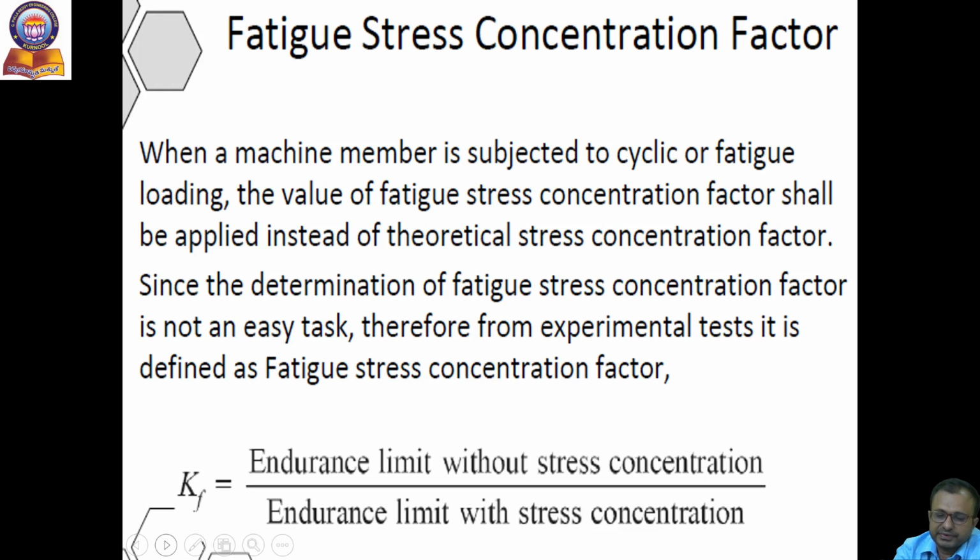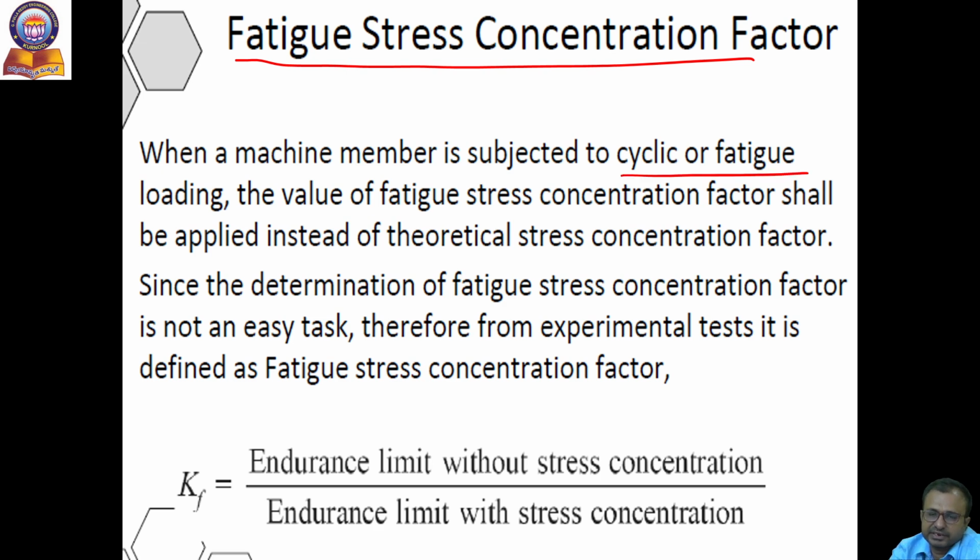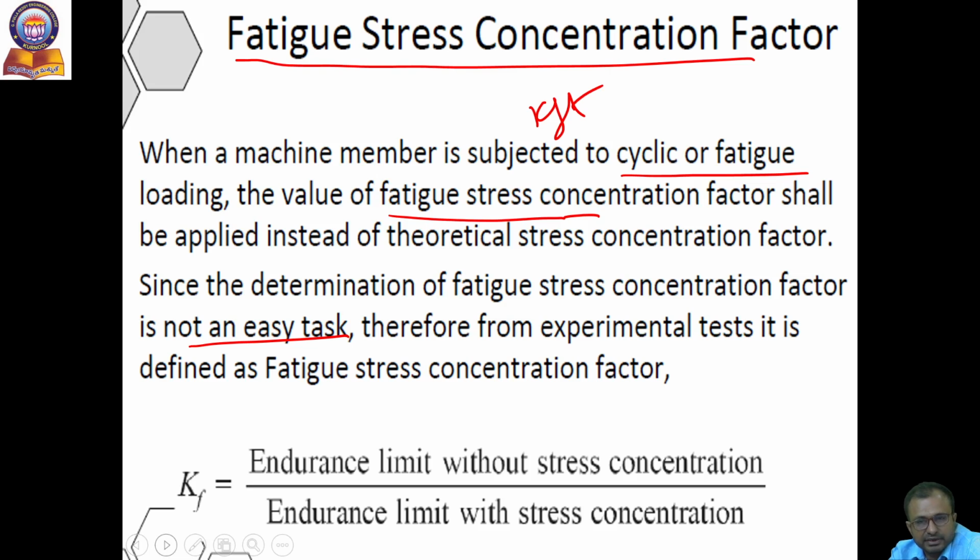Next one is fatigue stress concentration factor. In the previous classes, or previous videos, we saw stress concentration. Now we see fatigue stress concentration. When a machine member is subjected to cyclic or fatigue loading, the value of the fatigue stress concentration factor, that is KF, shall be applied instead of the theoretical stress concentration factor. Since the determination of fatigue stress concentration factor is not an easy task, it takes a lot of time, and that's why a lot of cost is involved.